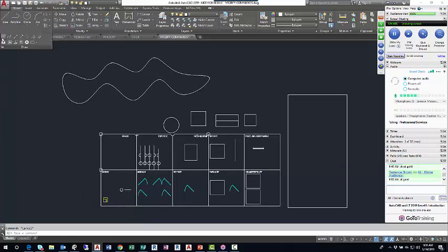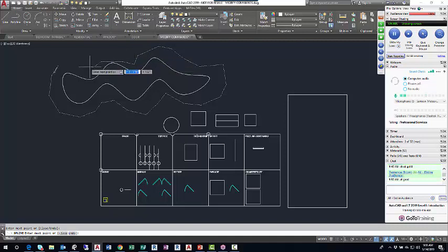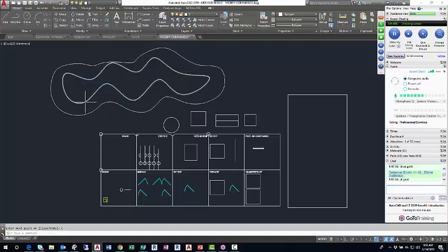Draw, I used Spline Fit. I'll use Spline CV, left click. CV is an abbreviation for Control Vertice or Control Vertex. So this one, you can see it a little better as I'm drawing it. I'm just moving and clicking, moving and left clicking, and then I'll close again. I'll right click and close, and that's the result there. So this is a tool where it would be a little tedious to try to create that shape with Polyline. So that's another advanced draw command.